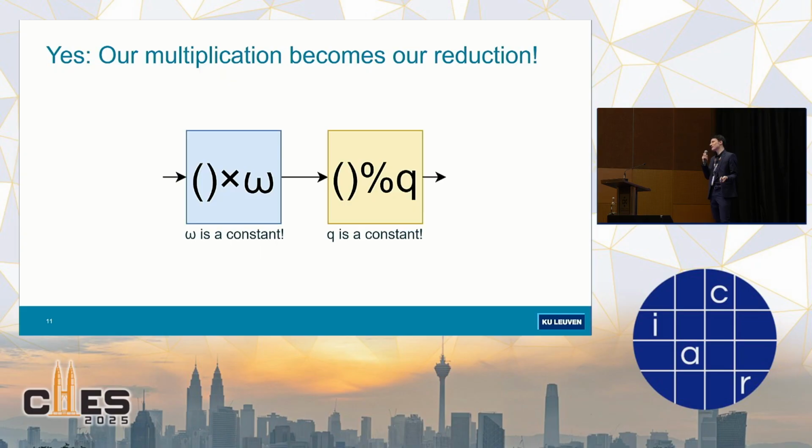Now, of course, you run into the problem that with some of these schemes, not all of them, but if you're talking BGV or CKKS, you're discarding the moduli as you go. You take your first modulus and you throw it away, then you move to the second modulus and you throw that away. And then you would have empty FPGAs, or empty NTT modules that are not doing any computation. So then it becomes a question of stacking enough modules on top of each other, really.